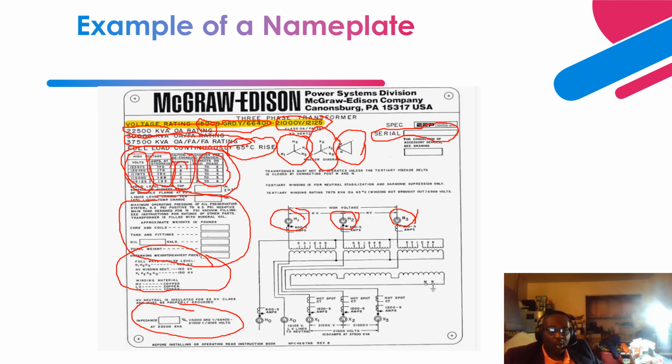So as you can see over here, the high voltage side is Y wound, and the neutral is grounded. So this is the neutral, right? As you can see over here, the H0. And the neutral CT is also 600:5. So this neutral CT basically goes below the bushing and is located in the bushing turret.